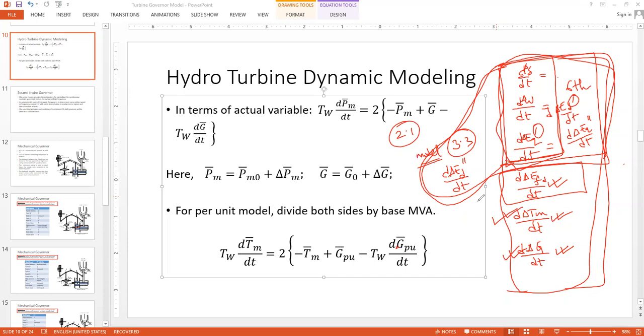Okay, so then exciter, again, we took a very simple model ultimately, but as we know, the amplifier or the voltage regulator dynamics is there. So there are a few more equations that could be incorporated here. And again, the fly ball dynamics is ignored here. You can include the fly ball dynamics. Probably there also we did some simplification. So all these models are still pretty simplified, okay? But you can go for much more complex models depending on your necessity of study and the complexity required for capturing any specific phenomena happening throughout your power system, okay?